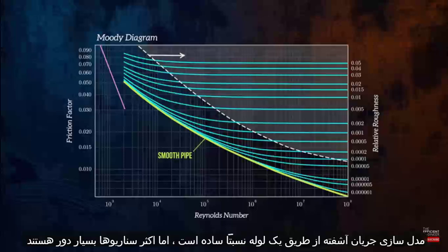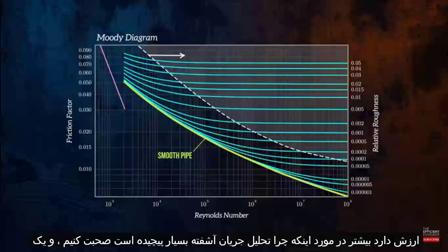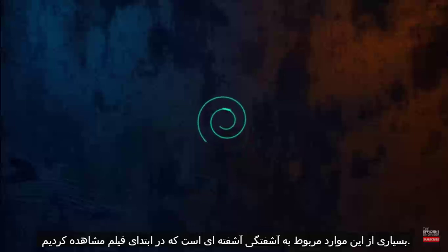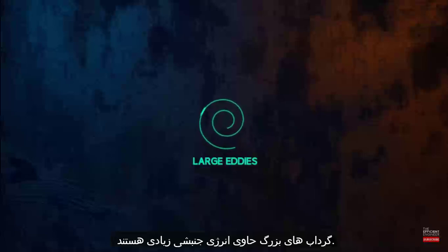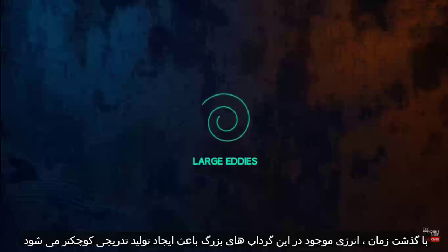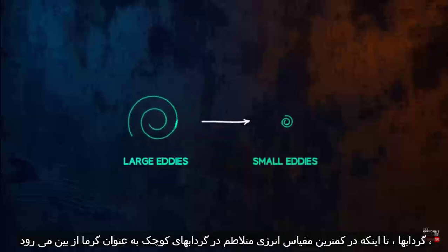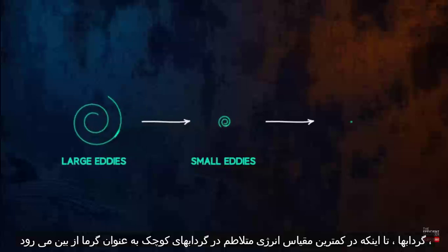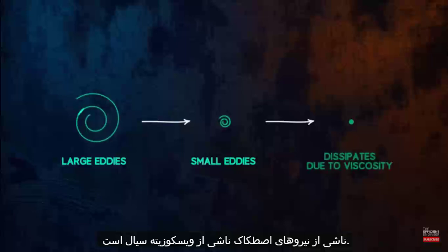Modeling turbulent flow through a pipe is fairly simple, but most scenarios are far more complex. It's worth talking more about why analysis of turbulent flow is so complicated, and a lot of it has to do with the turbulent eddies we saw at the start of the video. Large eddies contain a lot of kinetic energy. Over time, the energy in these large eddies feeds the creation of progressively smaller eddies, until at the smallest scale, the turbulent energy in minuscule eddies dissipates as heat due to frictional forces caused by the fluid viscosity.